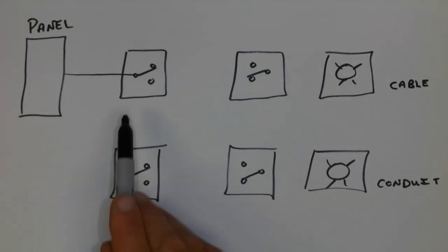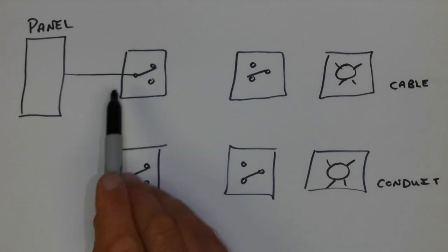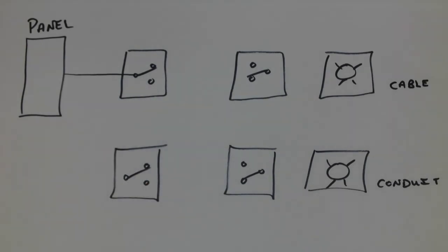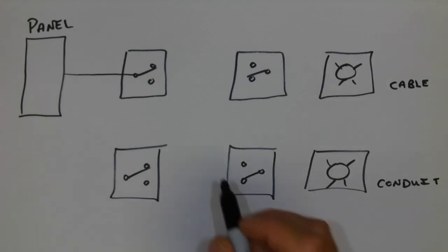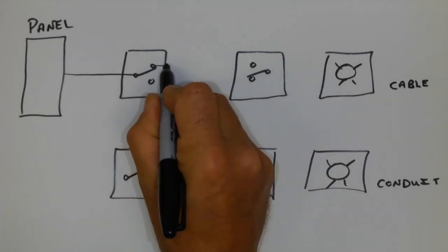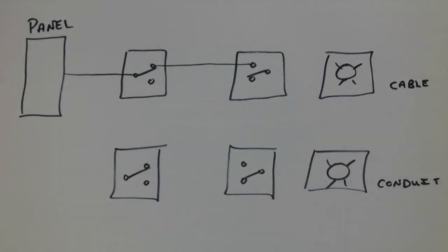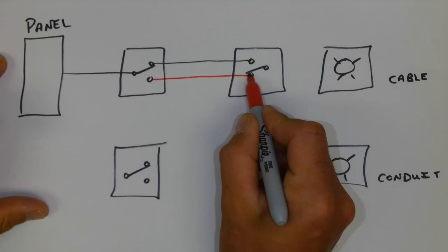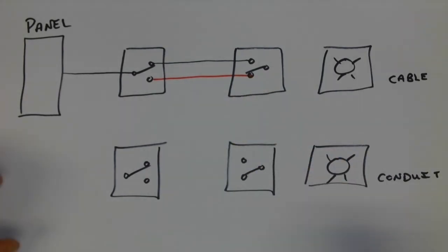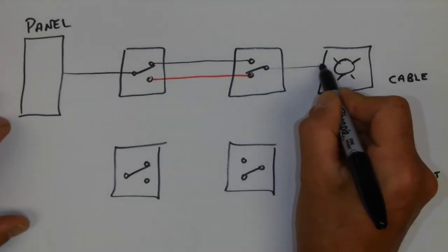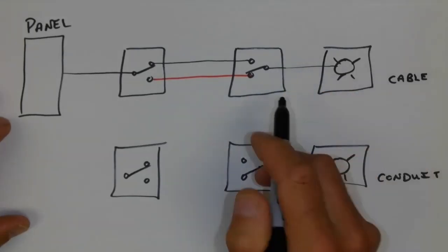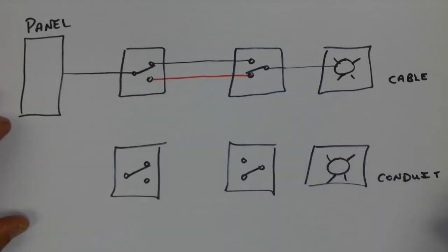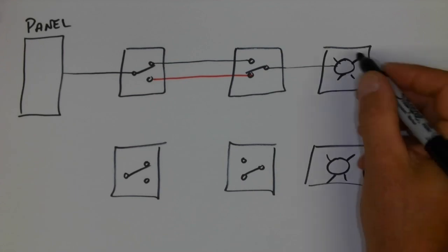And the light switch itself, the common conductor, is typically colored differently, or it will actually have the word common written beside it. Between these two terminals we have travelers. And then, again, a black conductor connecting our common back to the light itself.